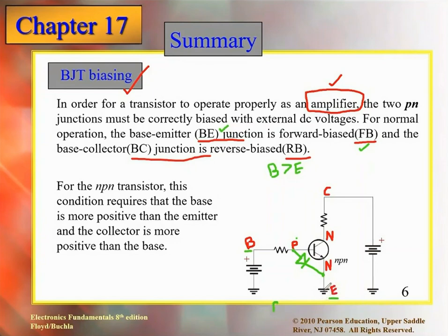It is connected to ground. Can you see this? Yes. So it is 0. So if I apply a little bit of positive voltage at the base, it will be in forward bias. So I am connecting positive voltage here. It could be any voltage. For example, let's suppose 5 volt positive. Is it going to be in forward bias or not? So quickly, it will be in forward bias.